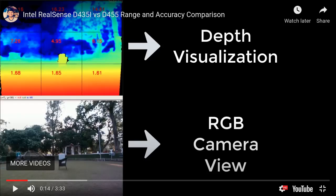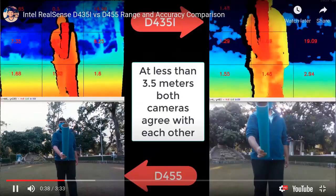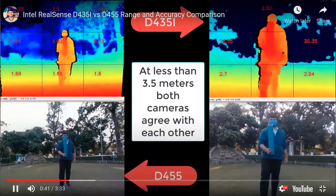And what I've done is divide this entire view into a 3x3 cross section, and I have printed the minimum distance of what I can find in each grid cell. So for example, the land is 1.65 meters away, whereas those trees in the background are 14, 15 meters away, as can be seen on the top. The rest of the videos are going to have a similar representation, and now you know what the red values are, and what this grid is. So yeah, just a static test of how well these cameras function.